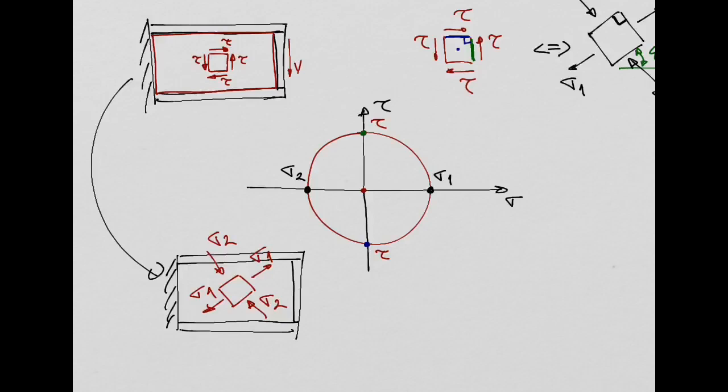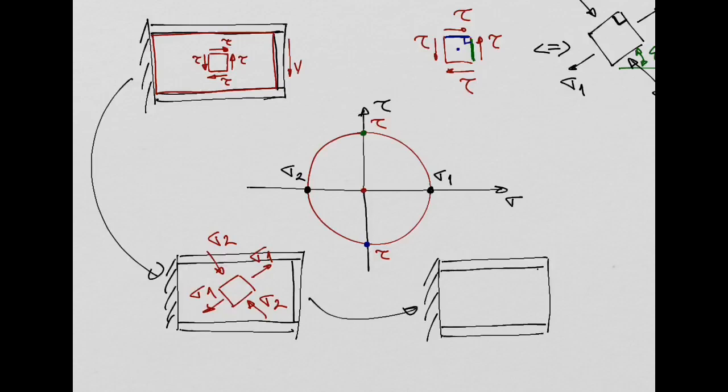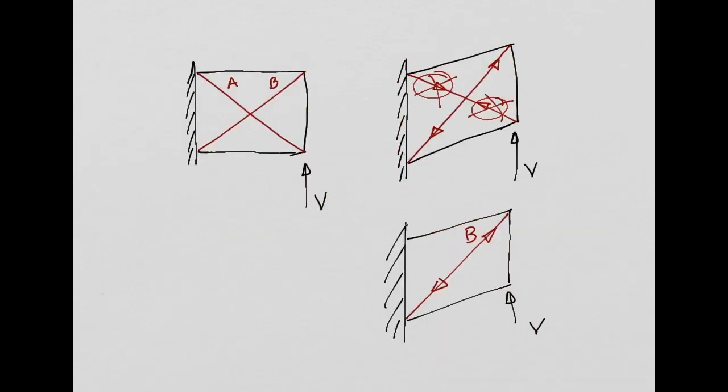And then what is going to happen is, after it buckles, my web will be carrying a stress which is going to be only sigma 1 in tension. Because once it buckles under the action of this sigma 2, it will not be able to carry the load in that direction of that compressive stress, right? And then this is when this analogy comes with this example, right? Yeah, same thing, exactly the same thing.